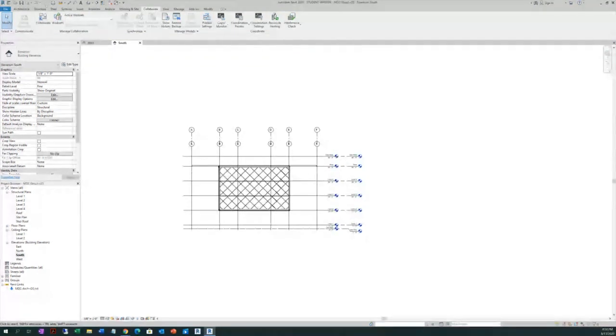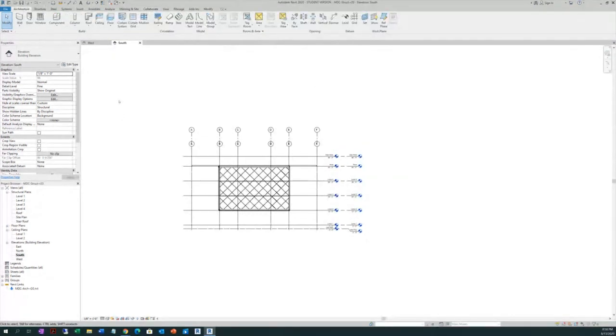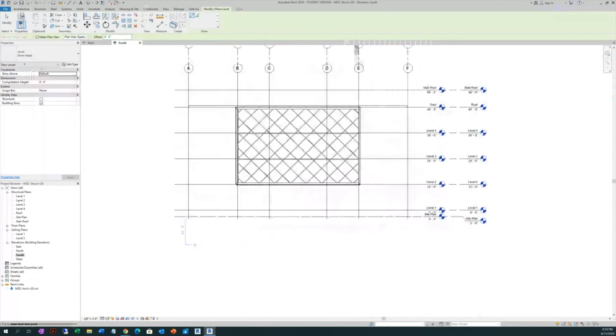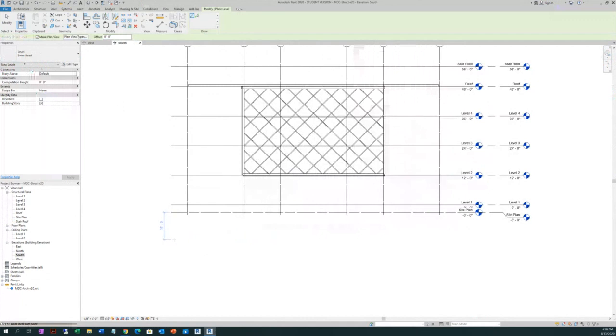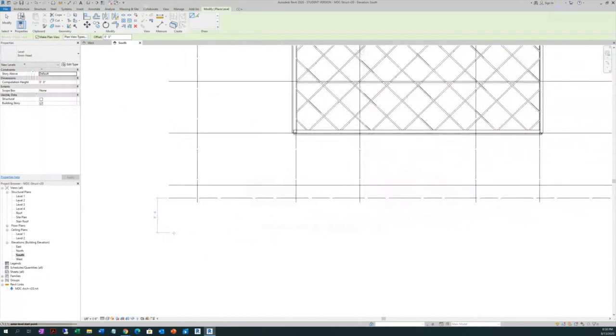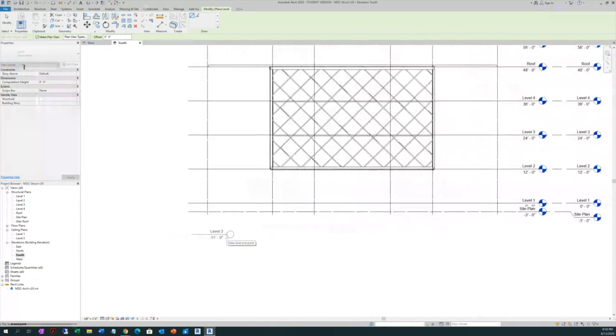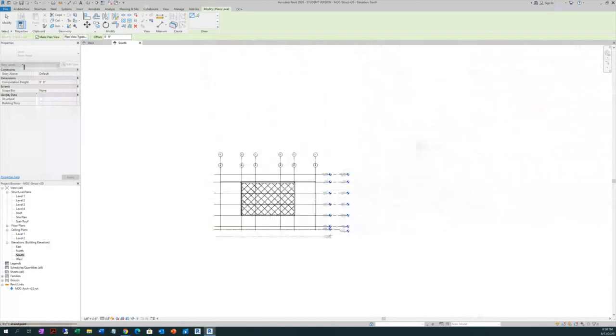So go ahead on your architectural. Then on the Revit, look for the data. Look for the levels here. Levels, and then under your site plan, place 8 feet. You can even place it from your keyboard. 8 feet? 8 feet. Okay, -8.